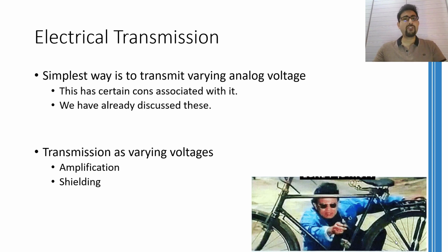Therefore, this way of transmission of signals is only utilized in a very low cost application or where the signal voltages are considerably higher than the magnitude of the noise that can be induced in the signal. For example, for turning on or off the lights or any other electrical equipment, simple voltage signals are used because in this case the voltage running in the wires is quite large and cannot be affected by the noise which is present in the surrounding environment.